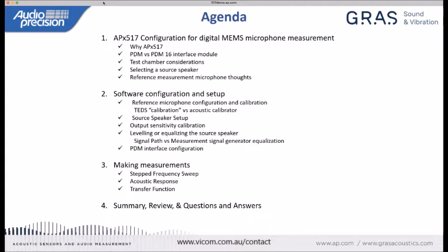But today we'll talk specifically and demonstrate specifically testing a digital MEMS microphone array that has a PDM, or pulse density modulation, output, and doing that using our APx517 analyzer and PDM-16 input module, which is a pretty specific and apt solution to this challenge.